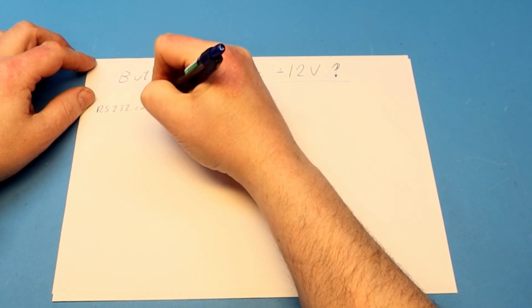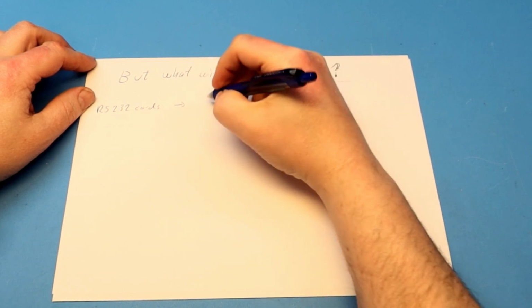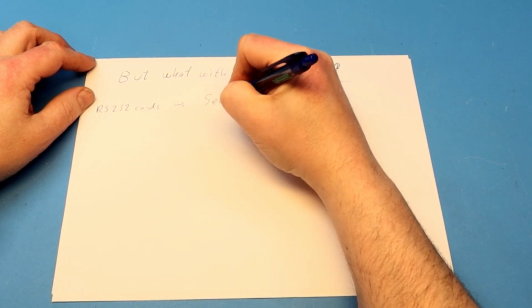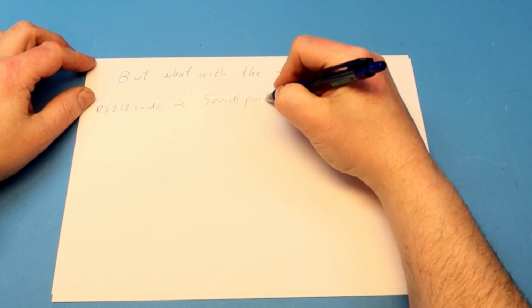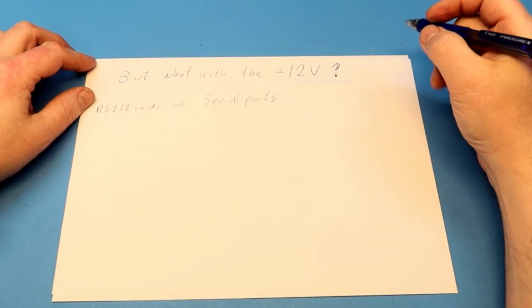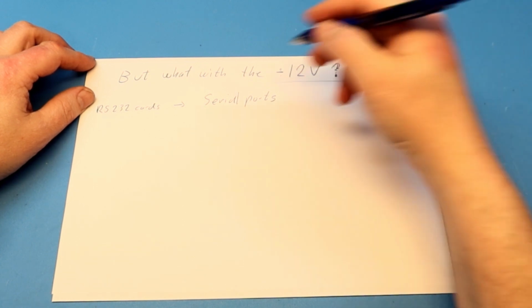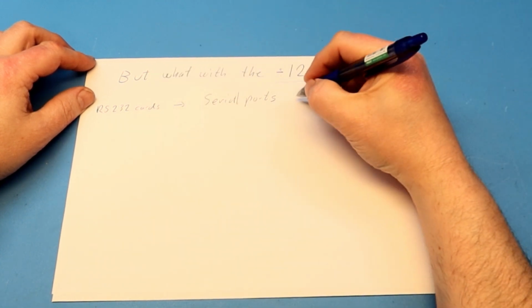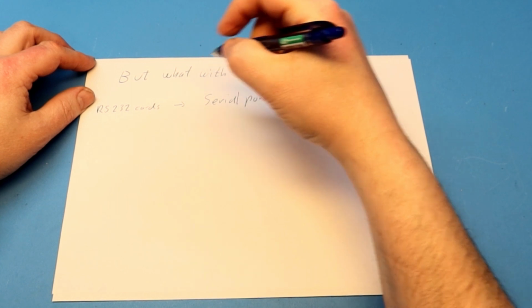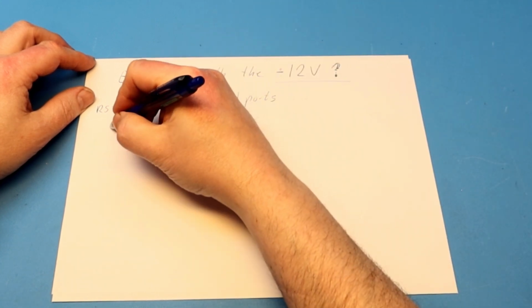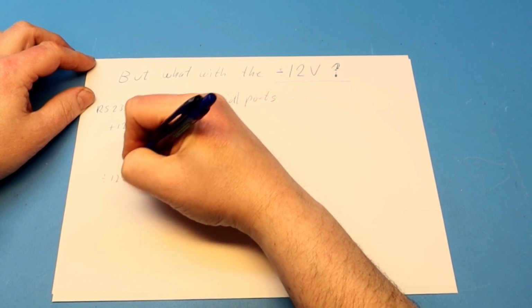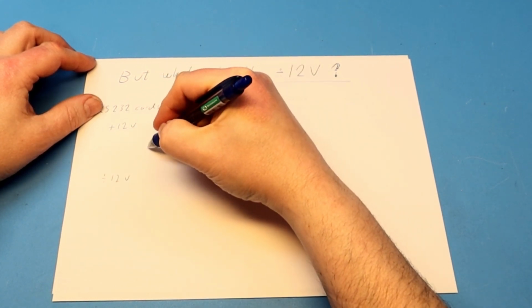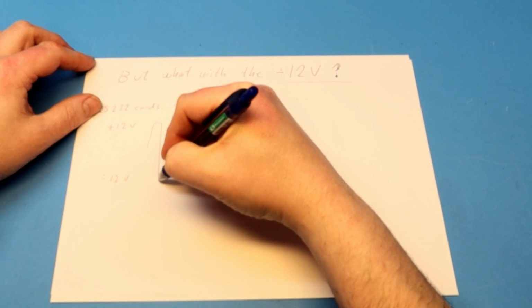And of course it's possible to have a charge pump or a small regulator on the main board and only supply the main board with 12 volt, and that will probably be what happens in the future, because the power supplies themselves will be cheaper if they only supply one rail of power, and it also means that the circuit and cabling inside is much cheaper.